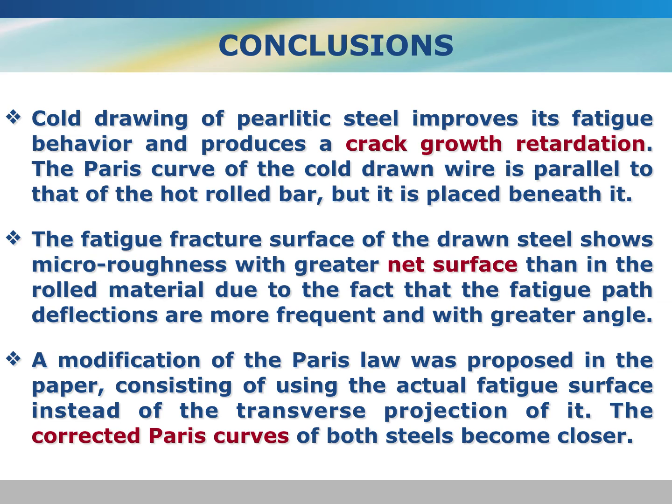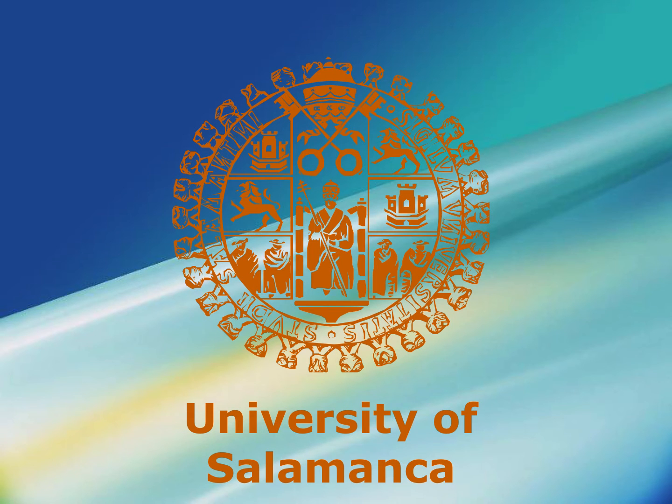A modification of the Paris law was proposed in the paper, consisting of using the actual fatigue surface instead of the transverse projection of it. The global mode 1 advance is the conventional Paris law, and we propose using the real crack advance, considering the zigzag shape and the micro deflections with their angle. The corrected Paris curves of both steels become closer.